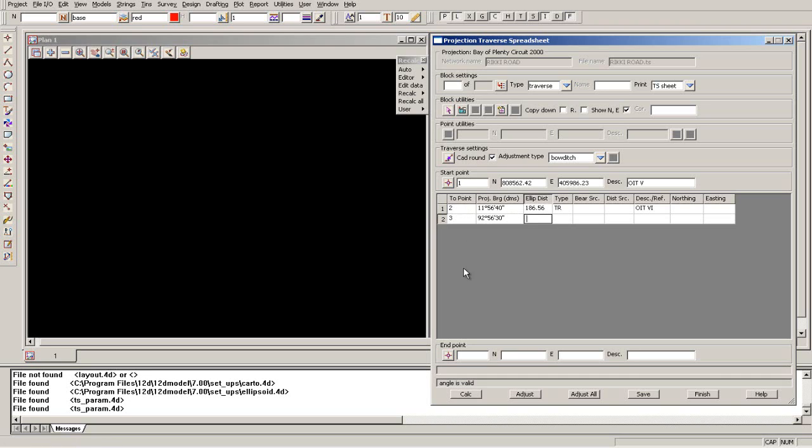Okay, and then this is all just off the plan, 92.5630, 163.47. We just put our traverse in, TR, we're traversing there, and that will give us old iron tube 7 in there, like so. And then we'll have a point round to here, which is iron spike 3, so we'll go 175.3610 for 78.96, and that's again a traverse.